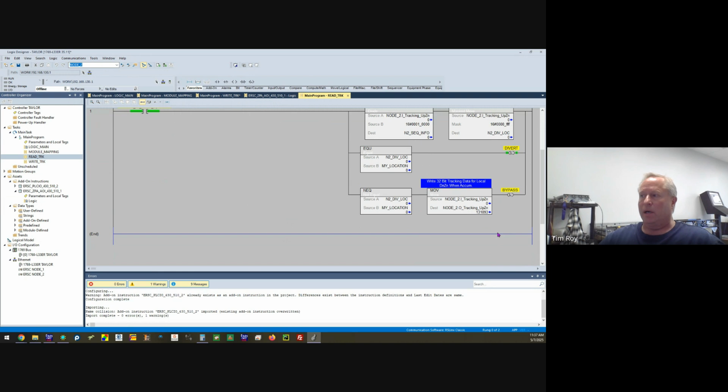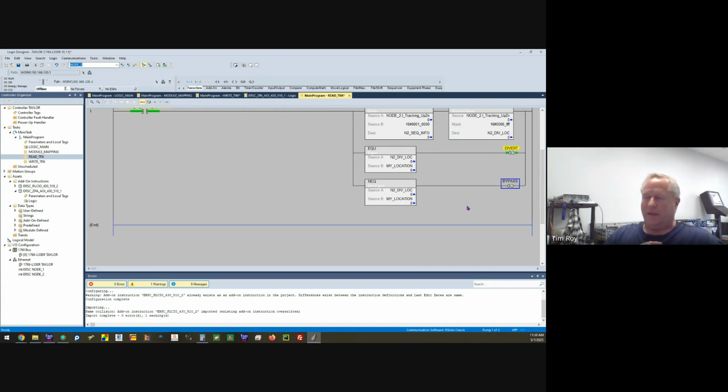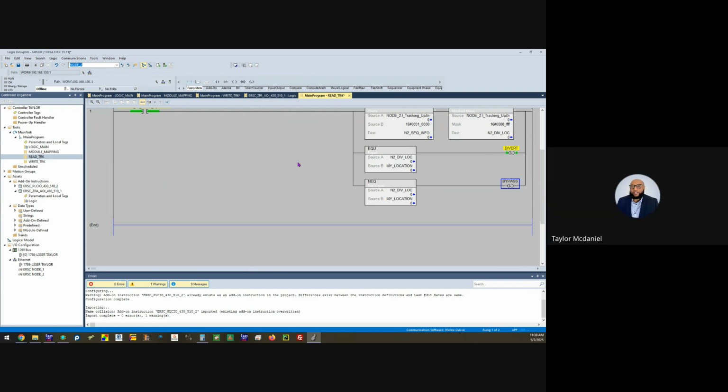And then based upon your tracking information, do we divert here or do we bypass the load? This step right here where we're looking at the tracking from the upstream, we don't have to move it to the downstream. That will happen automatically because they're in ZPA and they're talking to each other.